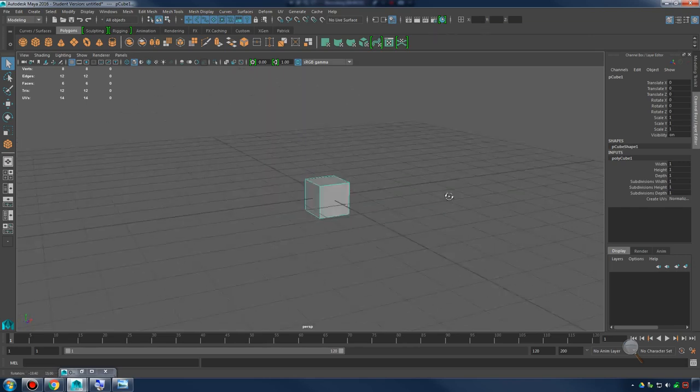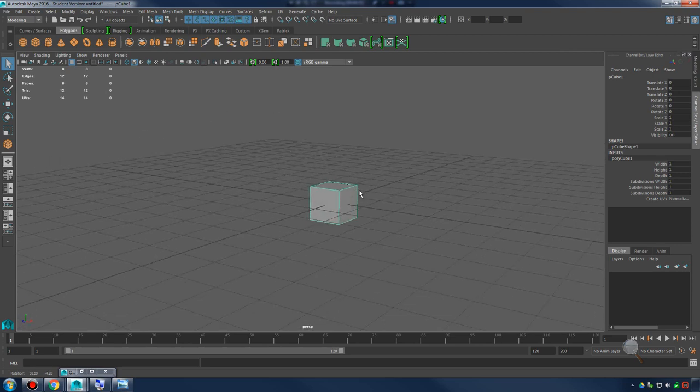All right, so the first thing we've got to figure out is what direction is what. We're going to set in our own values in our channel box. We're going to do that by using the scale values here. So I know that I want my steps to be about 7 inches, 8 inches apiece. And the very first slab we make is going to be our first step. So I want it to be a certain height. So I'm going to do maybe a 0.75. That'll give us about 8 inches, 75% of 12. I'm going to guess that's about 7 or 8 inches there.